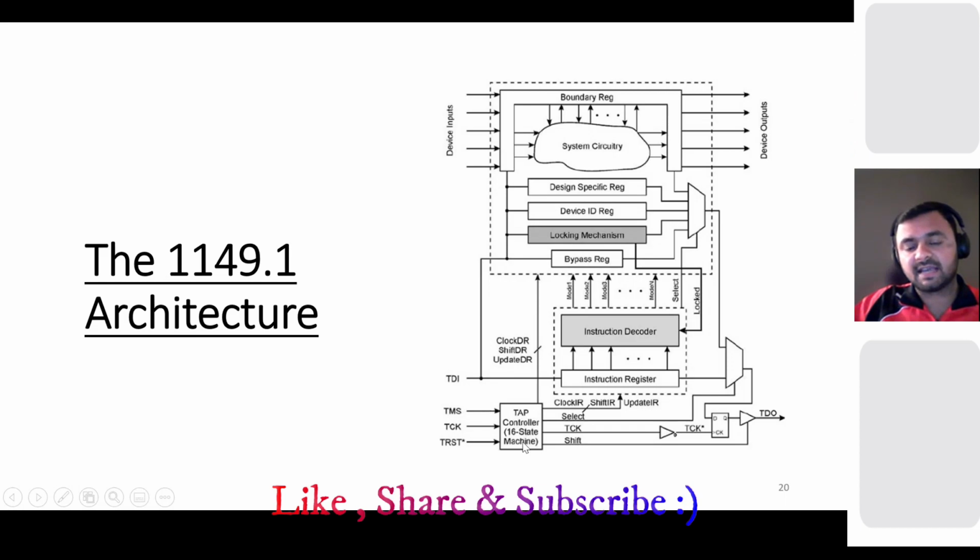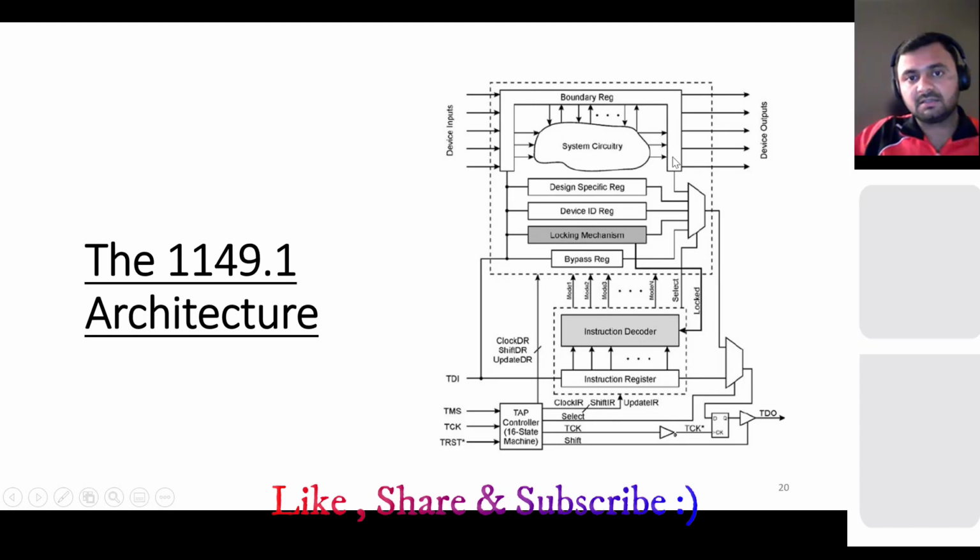So basically we have this TAP here, which is a 16-state machine. And we have TMS, TCK, TRST, TDI, and TDO. These are the 5 important signals. They are mandatory, apart from TRST. From the chip top, that means from the top level, you have test data input, test data output, test mode select, test clock, then test reset. Test reset is optional. I will tell you why it is optional. So at least these 4 we need, or these 5.